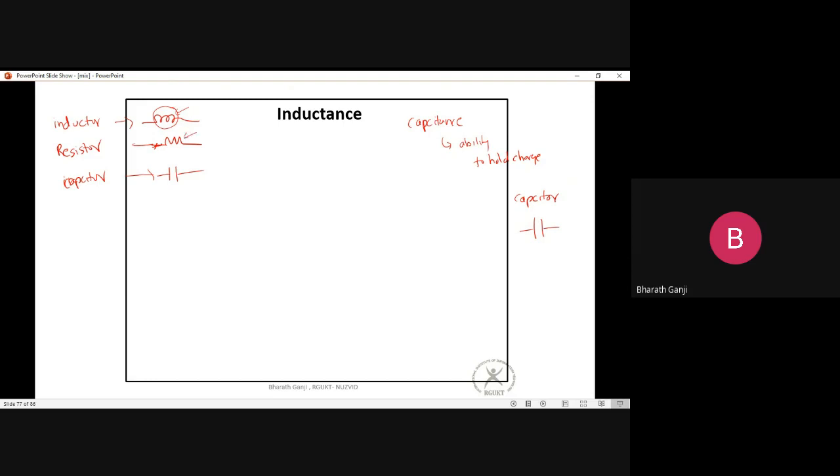Wherever you have placed your resistor symbol, that is the location where you have the resistive effect, and the capacitive effect is only between the plates. But usually, when we go for higher frequency devices, in higher frequency circuit designs, these effects are not lumped in some location, but they are distributed over the network. So in that scenario, it might be hard to find a solenoid-like loop, or you might not see a capacitor as two plates, right? Because there we deal with the distributed effects.